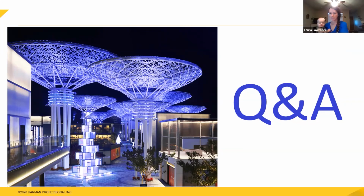Okay, next question. For terminating electrical and data connections on in-ground fixtures, can that be done in the fixture or does it require an external junction box? Yes, we do require an external junction box, which comes as an external accessory. So we need to make a pit, and we need to first install the junction box, and then the fixture will be placed into it.